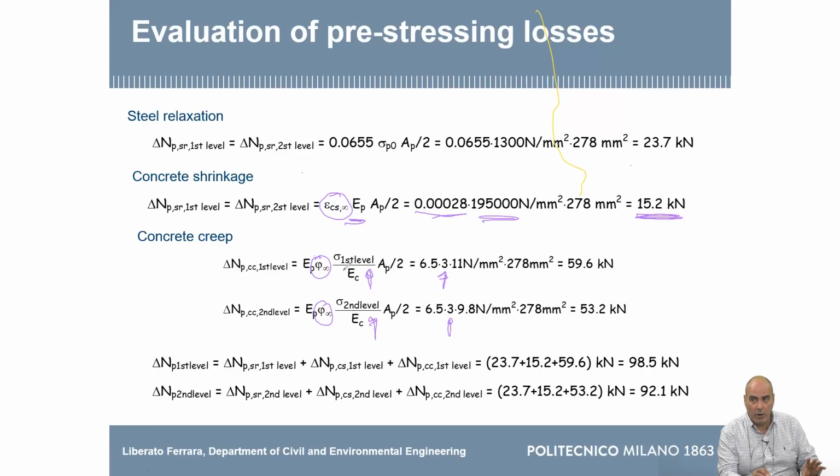Divided by the Young modulus of concrete, you have a strain in concrete, and this is elastic strain. Stress divided by Young modulus is elastic strain. So this here is concrete elastic strain. If you multiply by the creep coefficient, we use the notation phi, the creep strain is phi times the elastic.